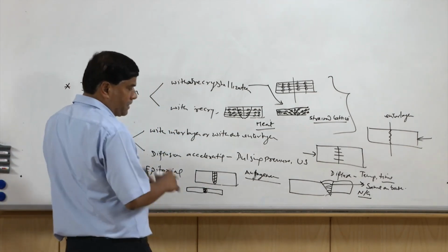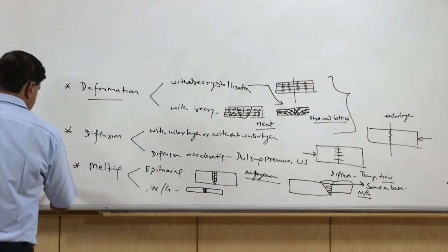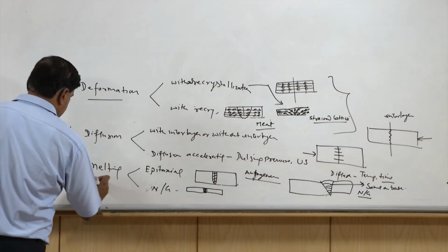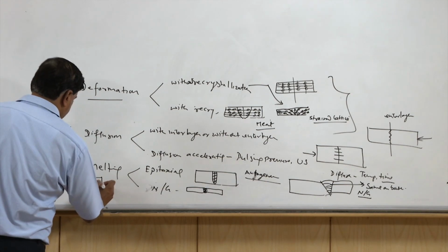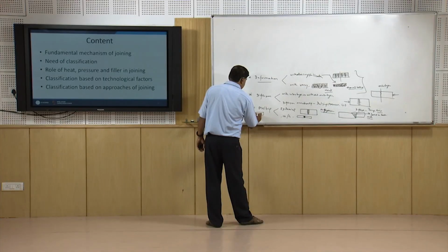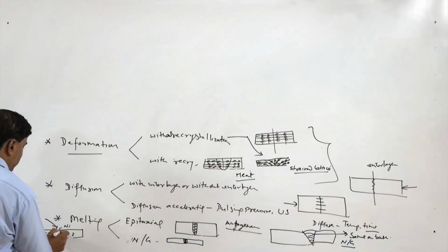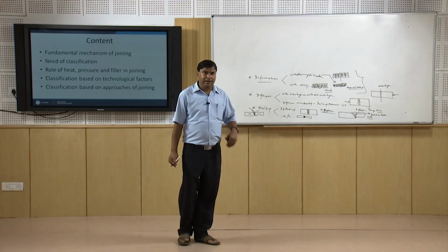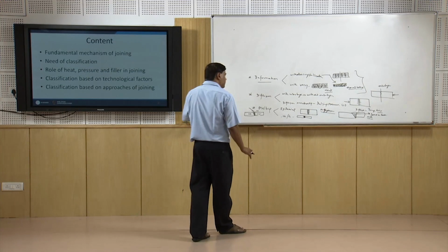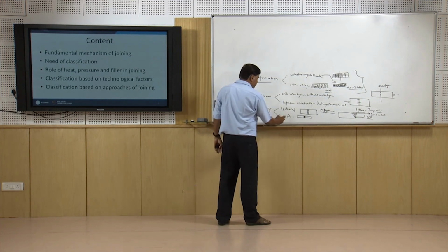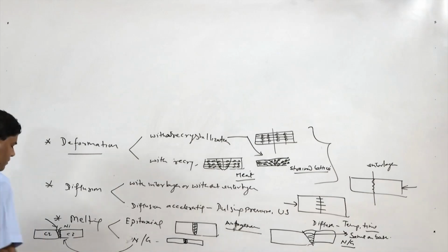But for specific requirements, sometimes the components to be joined are welded using a filler of different composition. Like, in the case of cast iron, it is common to use nickel as a filler metal. So here it is completely different. Cast iron has a BCC structure, and nickel has an FCC structure. Because of the significantly different filler metal, first nucleation and then the growth mechanism is involved in the course of development of the welded joints.